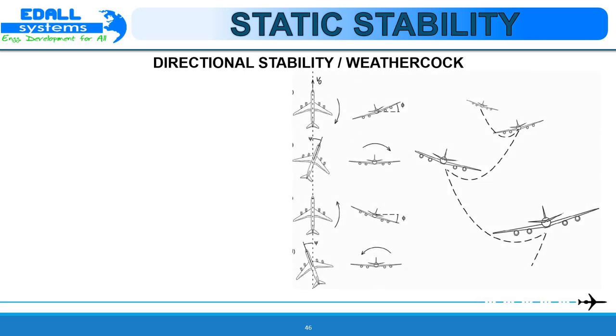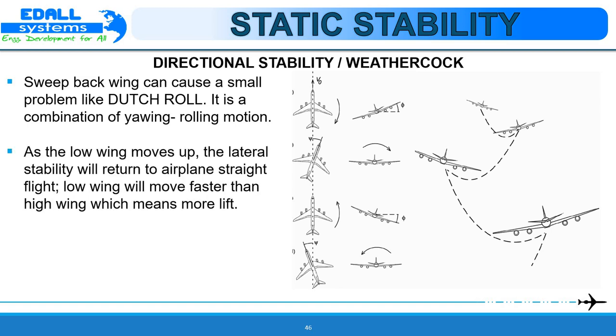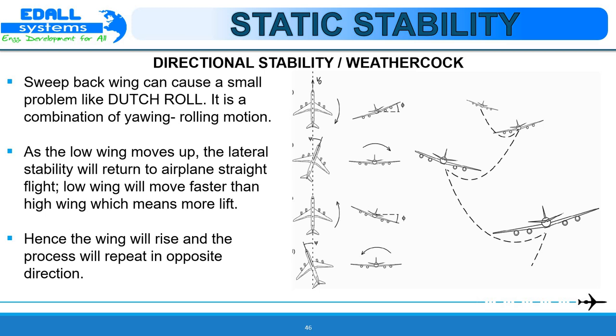The Dutch roll mode is a classical damped oscillation in yaw about the z-axis of the aircraft, which couples into roll and, to a lesser extent, into sideslip. The motion it describes is therefore a complex interaction between all three lateral directional degrees of freedom. Fundamentally, the Dutch roll mode is the lateral directional equivalent of the longitudinal short period mode.